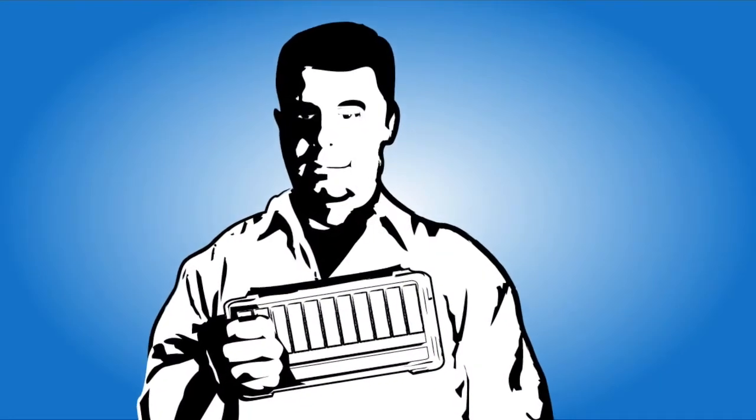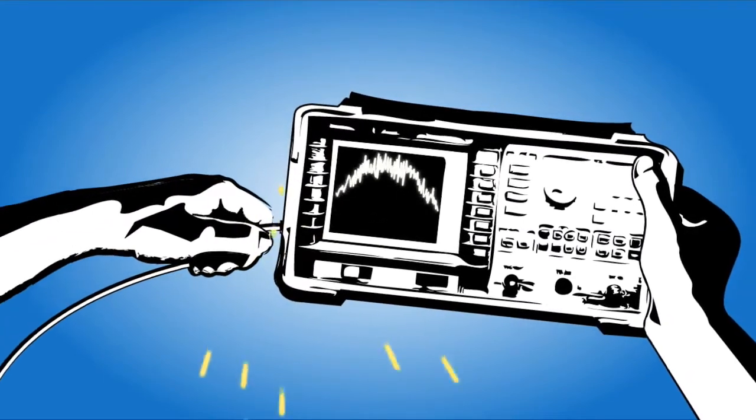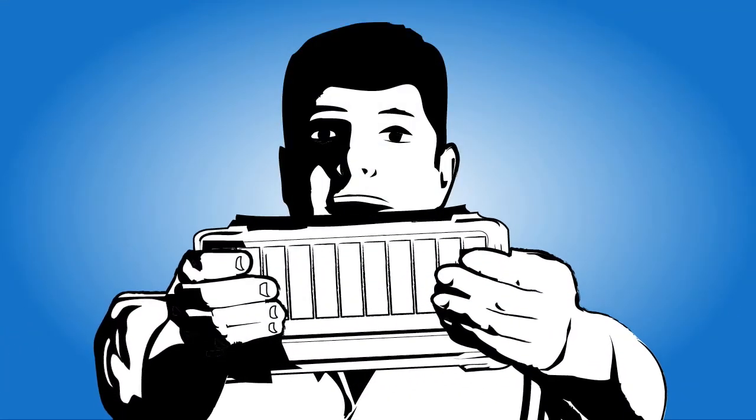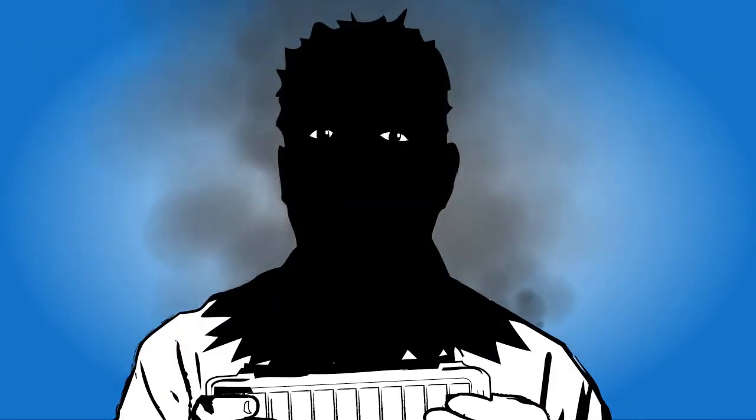There is one company that calls the difference between the displayed average noise level and the damage level, the signal level that will break the instrument, dynamic range. This is not dynamic range either. There really isn't a standard term for this value.